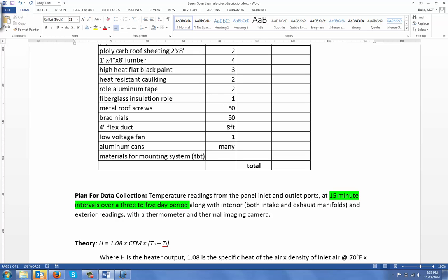And this is not a 242 thing, but it's more of a 235 thing, which is like heating degree days. Because from there you'll say, I'm this many degrees below where I want to be, I'm putting this much power in. That's what you'll get from these 2 temperature readings, and that'll basically tell you, is the system size sufficient to do that? Okay.